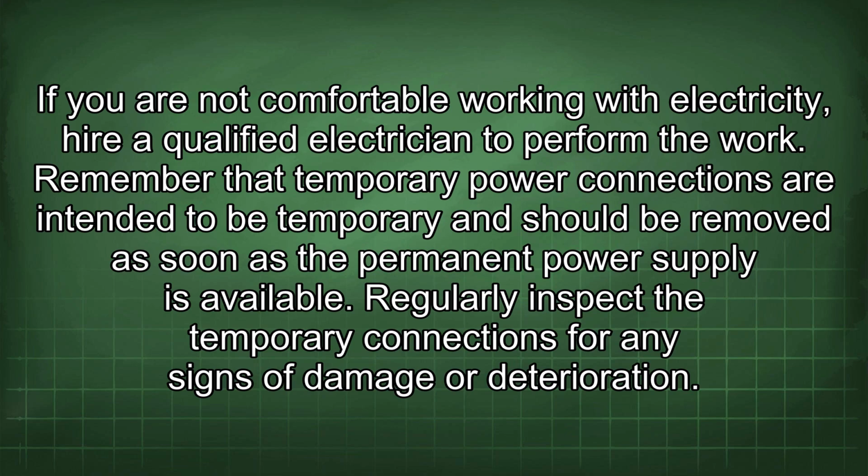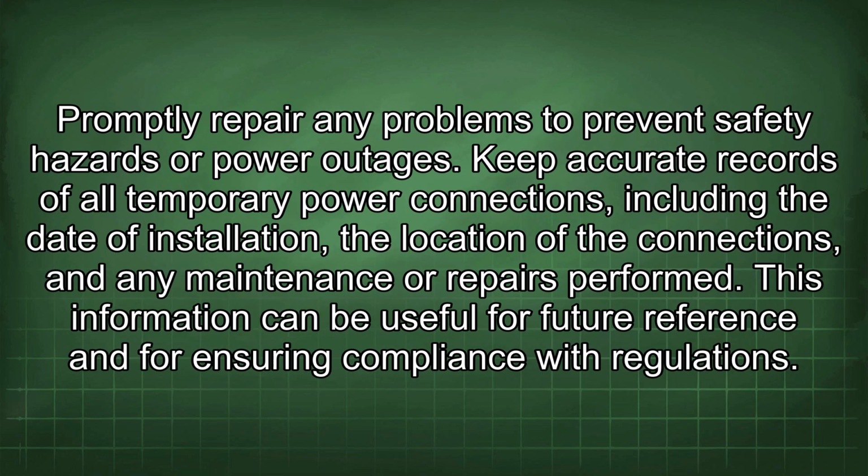Remember that temporary power connections are intended to be temporary and should be removed as soon as the permanent power supply is available. Regularly inspect the temporary connections for any signs of damage or deterioration. Promptly repair any problems to prevent safety hazards or power outages. Keep accurate records of all temporary power connections, including the date of installation, the location of the connections, and any maintenance or repairs performed. This information can be useful for future reference and for ensuring compliance with regulations.